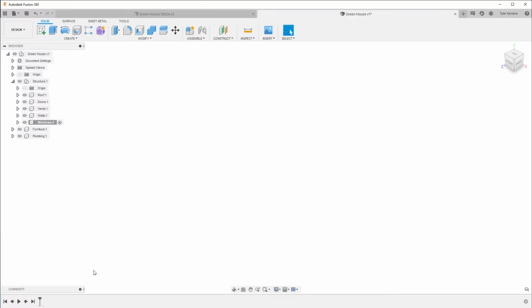And is this absolutely necessary from the start? I kind of think so. I mean, you can definitely get away with starting to create sketches, create bodies, and then converting those into components. But you'll have a lot of issues with your sketches straying off to where you'll see all of your sketches in this top level assembly. And in some cases, you can drag those into the individual components and not have an issue with it. But in some cases, you can't do that. They have associativity with other things, and changing the location of the sketches just doesn't work.